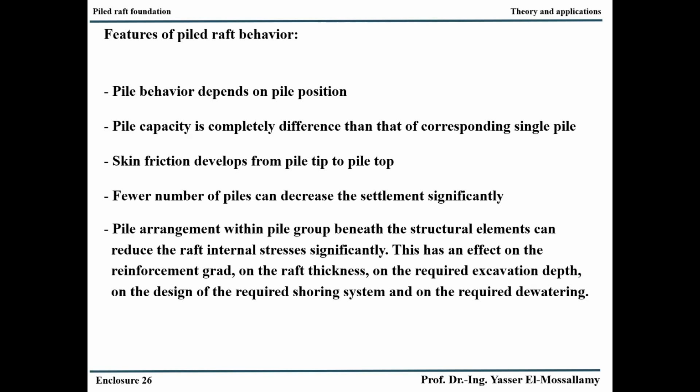In the German recommendation that is now referred to in the Eurocode, it is written that in the case of a wide raft foundation, we don't need to check the bearing capacity of the single pile. That means actually the piles can be designed near their limit capacity. This is not more than a plastic hinge in a frame action, as you know in concrete structures.